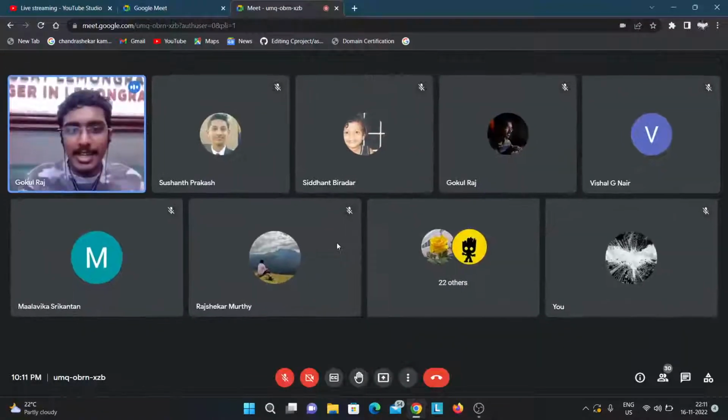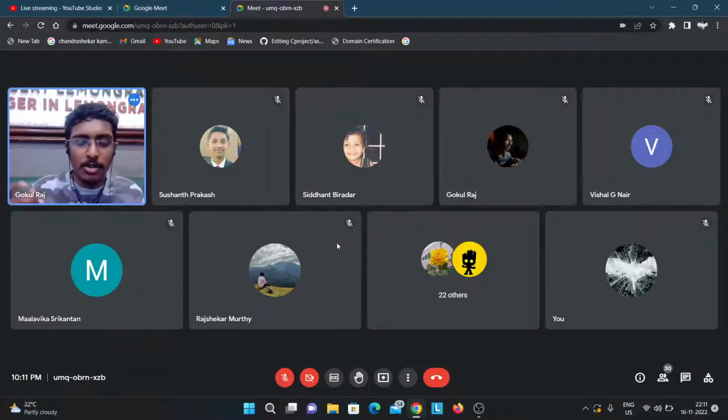And if you use an ESP or Node MCU, you can too. I'm just telling you, I'm not going to show you how. I will send you resources for that. If you have a Node MCU or ESP, you can actually connect it to the same Wi-Fi, use ROS serial in it, and control your robot using ROS with your mobile wirelessly on the same Wi-Fi network. So this is how you can use it in your real hardware projects.